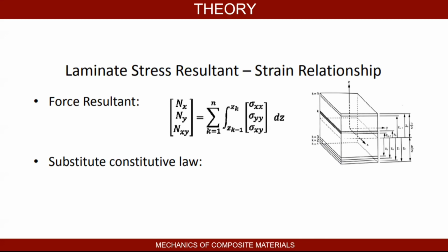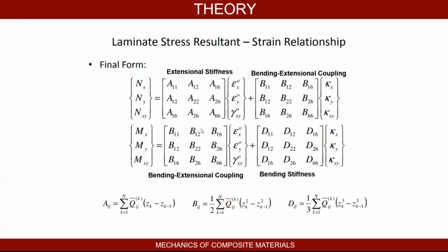but it can be a little tricky. So it's important to think about it as you're developing a boundary for each lamina about the midplane. So referring back to the problem statement, you have a stress resultant and a moment resultant, and you want to relate that to the strains about the midplane and the curvatures. And that's done with something called an ABD matrix.